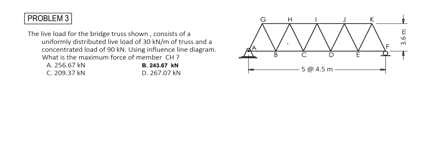To solve this problem using influence line diagram, we begin by placing a 1 unit load that would cross over the entire span of the beam. The distance from the support at A to the 1 unit load, we call this distance x. To solve for the reactions, let's call this R sub A, and this one at the roll support, R sub F. The value of the reaction is dependent upon the placement of this 1 unit load across the entire span.